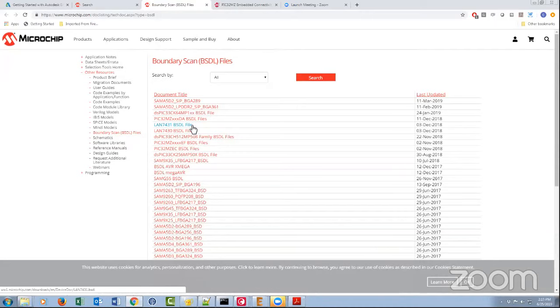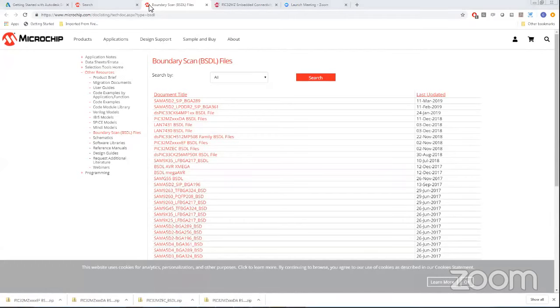Jorge, could I interrupt you just for a minute? Yep. I just wanted to explain because I know that everybody here is very experienced with Eagle, but for those that are not as experienced, I wanted to let you know that our library editor, when you're creating a component, consists of three stages. You have your schematic symbol, and then you have your footprint, and then you put it together. We call it like the glue. It's called a device.